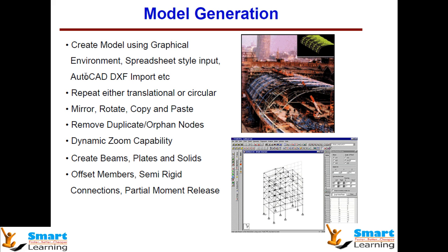You can reorder the beam numbers, column numbers, and you can adopt a particular sequence for understanding or recognizing the beam or column or slab or any element within Staad. You can remove any duplicates or orphan nodes where you don't have a proper node nomenclature. You can repeatedly use that. That particular concept we will look at in our session in brief.